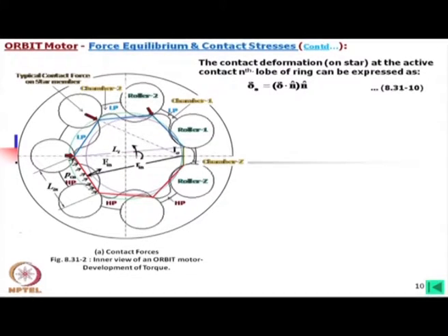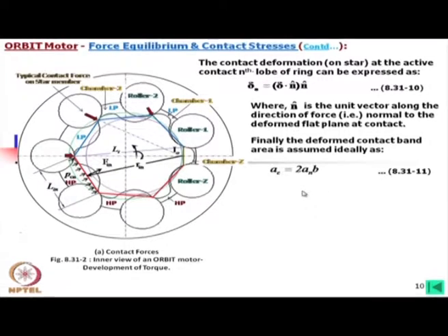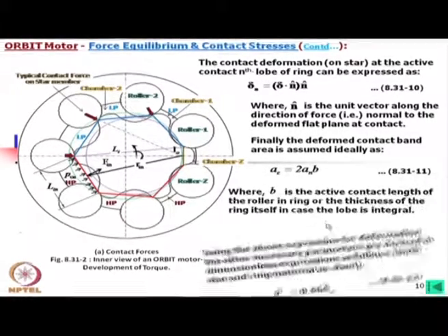We have considered deformations in any direction, then by this multiplication we find the magnitude of deformation along the normal line. For that we need these operations. Also, the actual area of the contact can be found out, because we have calculated the half bandwidth. So, the total bandwidth will be this much, and B is the width of this star or ring. So, we get the actual area.